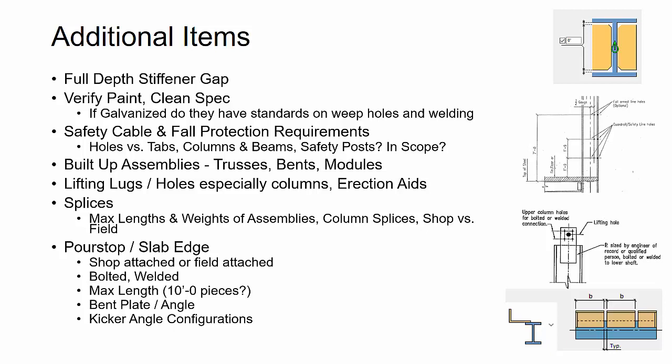Now, if you actually see a bent plate or an angle called out that's a structural size, 3/16 or larger, then you want to start asking the fabricator, hey, is this going to be shop applied or is it going to be field applied? Is there a maximum length to the pieces that you want? Some fabricators don't like 20-foot long pieces of bent plate detailed because, one, they may not be able to bend that length, or they may not be able to procure it at that length. And then also it's harder to handle.